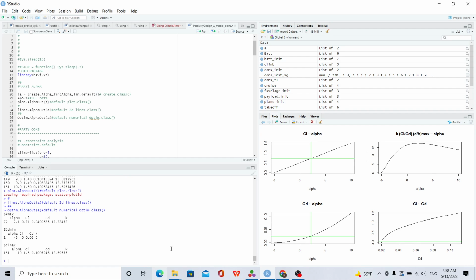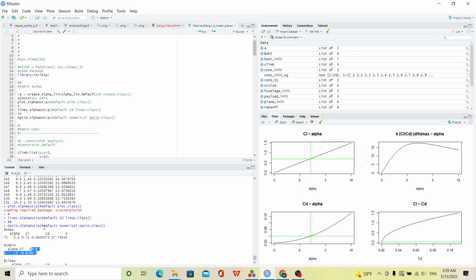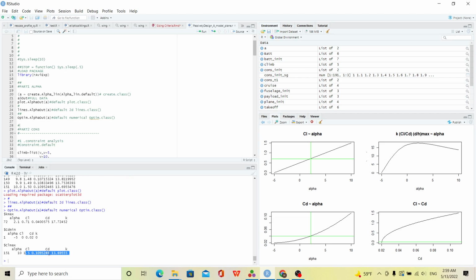So this is kind of used for diving, getting up to speed. The CL max, in this case, gives you more lift coefficient, and is used for takeoff and landing, and this one gives you more efficiency when flying horizontally, because this requires the least thrust to weight ratio.